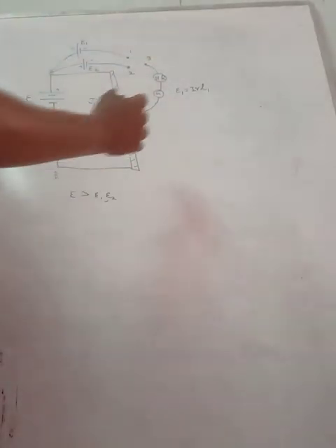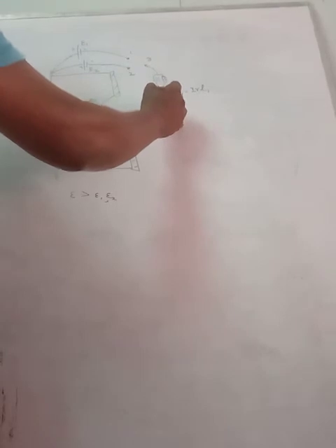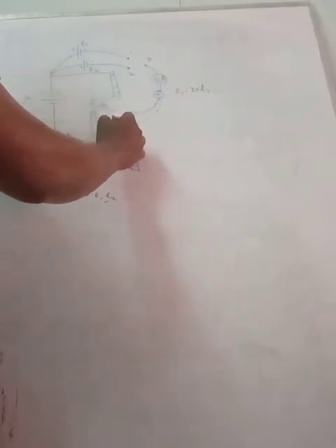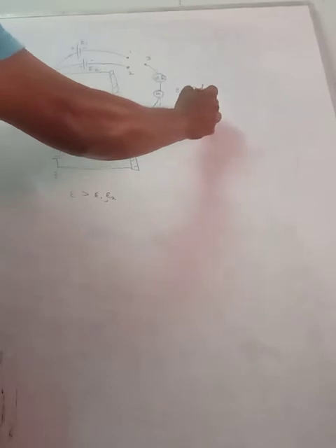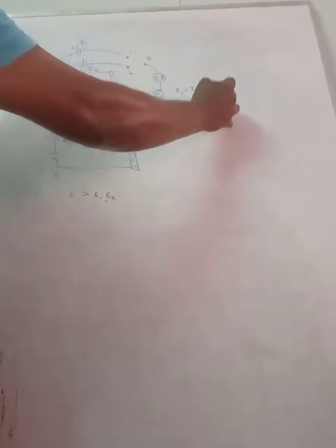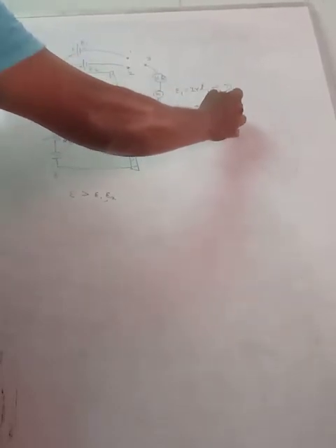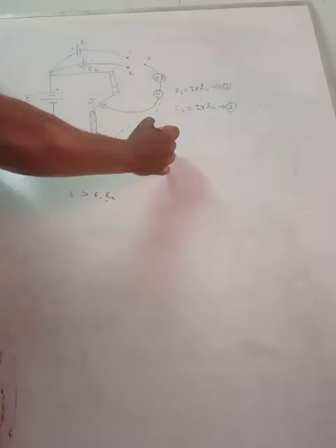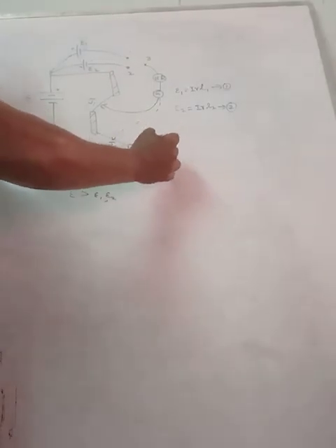So now, when the second battery is connected, it may find a new position. Let me take that position as J2. Now you can write, and here the balancing length will be L2. So you can write E2 is equal to IR into L2. Take this as equation 1 and let me take this as equation 2. Okay, now let us go with equation 1 divided by equation 2.